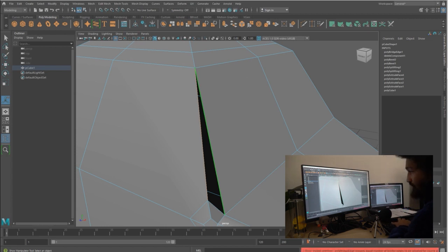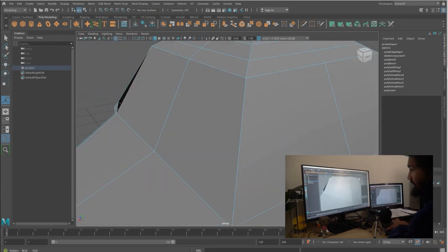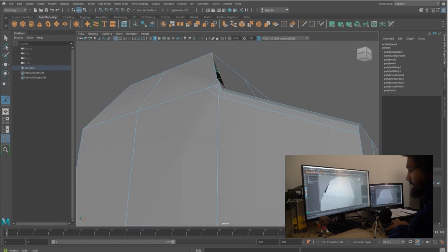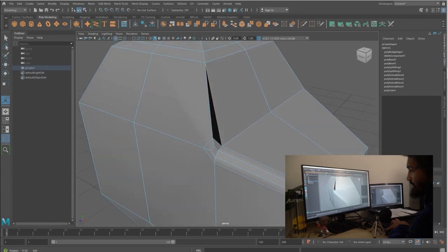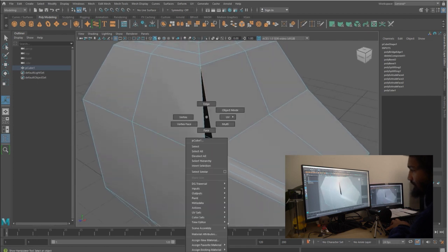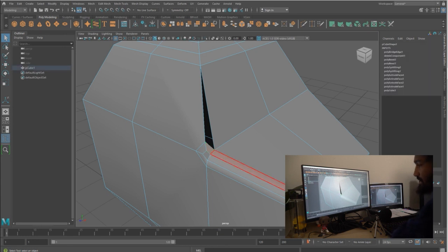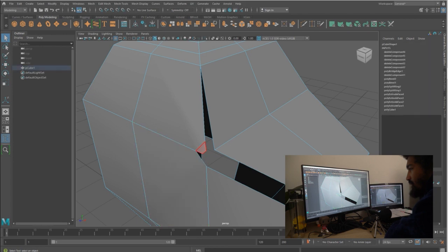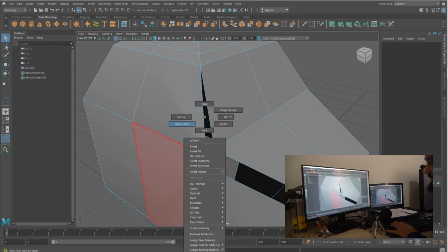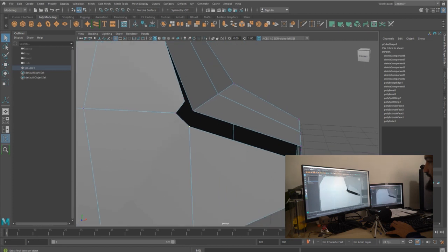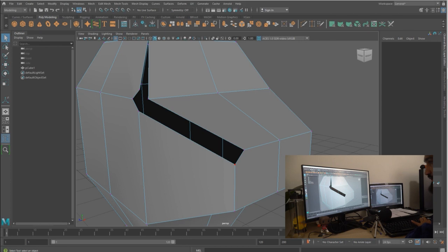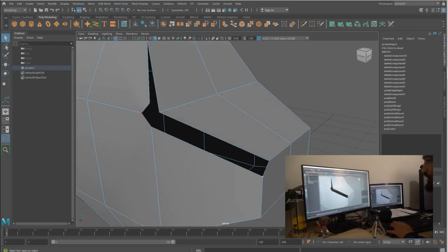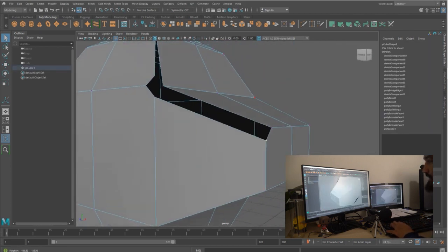We press G to do the last action, and you can see actually here and here. That's because I used some bevel here, so I can't reconnect this. This is one situation we can come across. We're just gonna delete the face here, this one, this one, this one, this one. All the faces we don't really need, and we're gonna put the vertices close to each other. We don't want this vertex as well and this vertex as well.